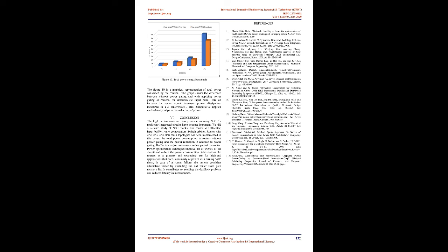The experimental results for the proposed method, simulation and synthesis, were conducted using Xilinx ISE version 2019.1. The power experiments with the proposed methodology are conducted on 2x2, 2x3, 4x4, 8x8 mesh topology routers. The NoC model is implemented using SystemVerilog. Experiments have been conducted on mesh NoC topology with and without power gating. Total power is the addition of dynamic power and static power. The comparison is between the model without power gating and the model with power gating, for different size mesh topologies, for dynamic and static power.